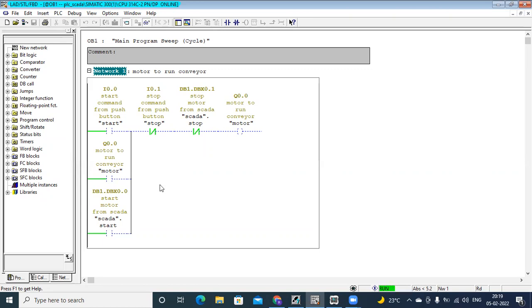Now, here I made one predefined program in PLC, as there should be a program present in PLC. So I'm using another address here. You can see DB address. DB means it's called data block address in Siemens. So it's additional memory blocks, which is an internal memory for storing temporary information, temporary data in your PLC.